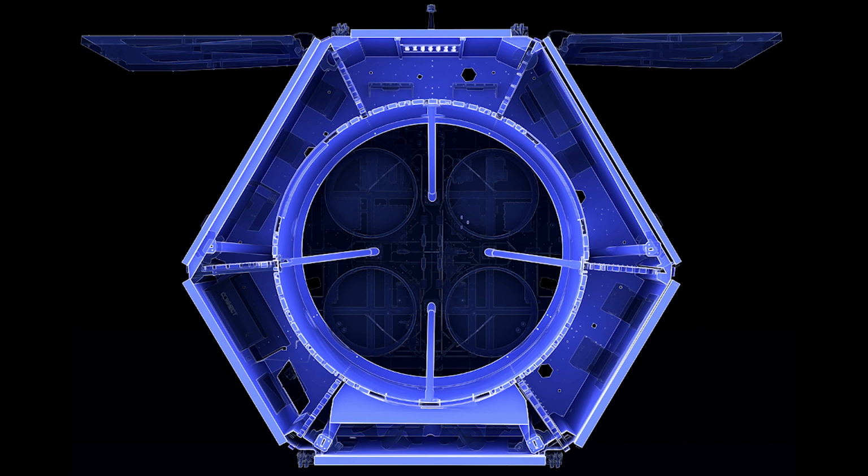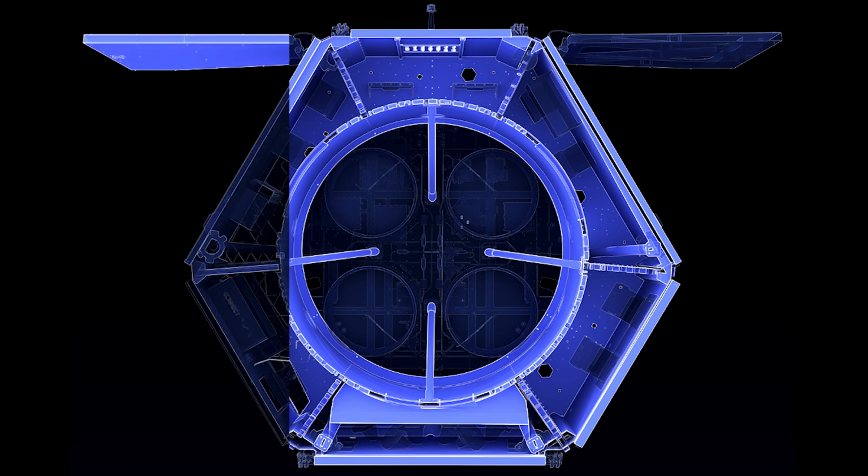It contains six compartments, or avionics bays, that house key electronics and components for running the rest of the spacecraft. It's made of a central cylinder with a top deck that supports the rest of the observatory and a bottom deck that interfaces to the rocket during launch.